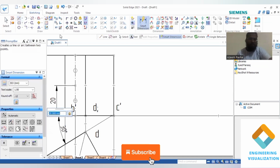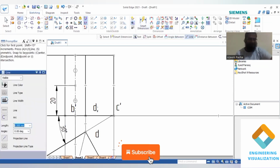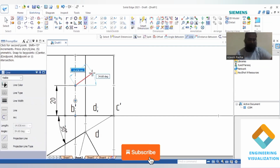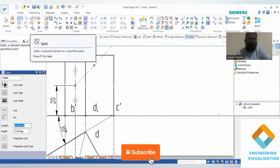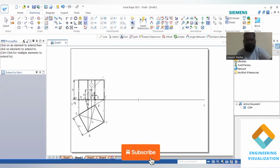Now you take a line, section plane, we have to draw an angle line for an angle of 45 degree here. You can give the angle 45 degree, enter, then you just draw a straight line. So we need to draw an angle line. Now using the extend to next command, we can extend the same section plane downward also. Okay, so it is extended. Now you can show the angle.